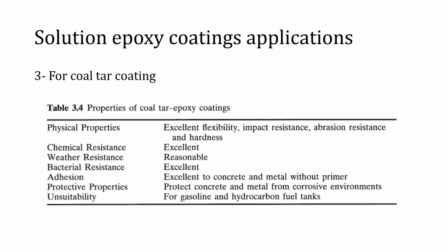Therefore, these coatings exhibit excellent flexibility, impact resistance, abrasion resistance, and hardness, and also they are resistant to a wide range of environments, including freshwater, seawater, sewage, detergents, dilute mineral acids and alkalis, exhaust gases, etc., which make them extremely durable, especially to protect concrete and metallic surfaces in submerged and non-submerged conditions.